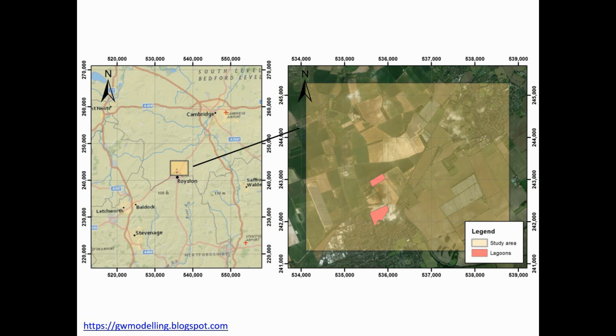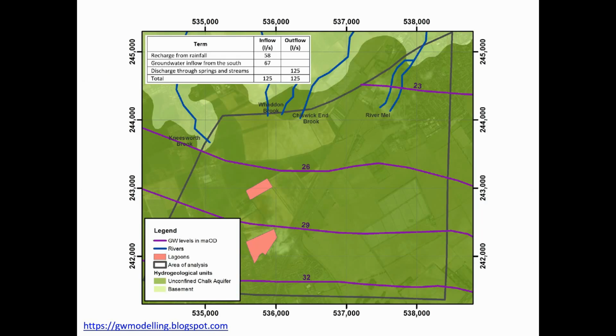The plume is moving to the north within a chalk aquifer which has high transmissivities associated to conductive fractures. Although the chalk has a high primary porosity, the pores do not contribute to transmissivity because of their very small size. That said, there is chloride diffusion happening between the fractures and the primary porosity, which induces retardation in the